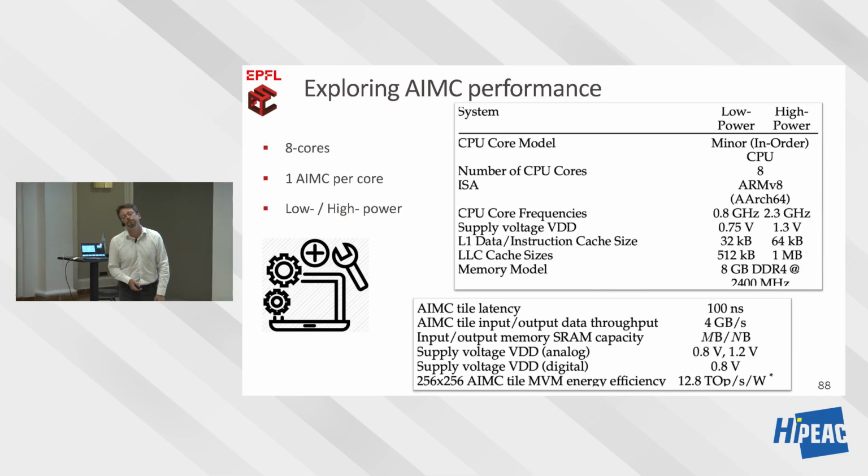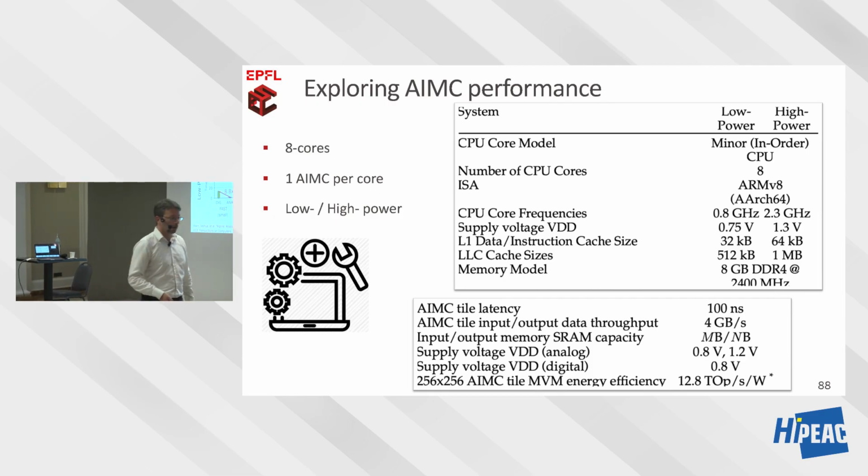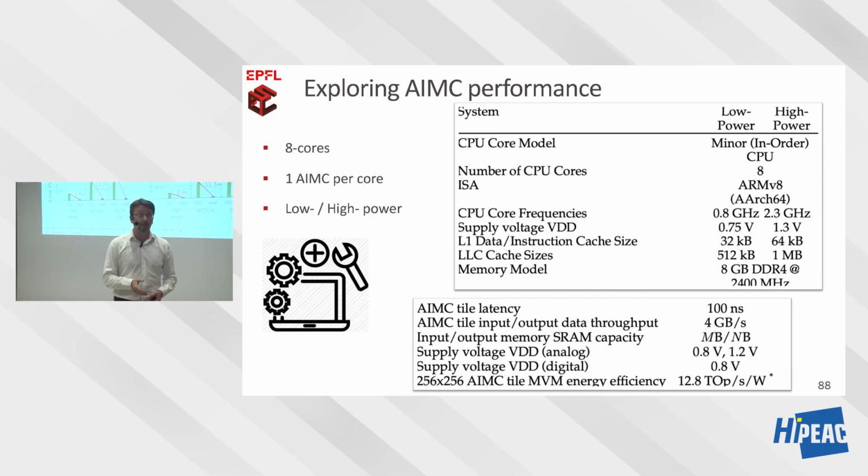Please. So how far in the abstraction layer do you have to go to model the crossbar itself? So gem5 is an event-driven simulator. So you have to tell the simulator, in response to a given input, what will happen after a given number of clock cycles. So this is the level of abstraction which it gives you. For example, if you have an integer unit, you can say that if you activate that integer unit and you want to do an addition, your addition will be ready after 2 clock cycles. Something like this.